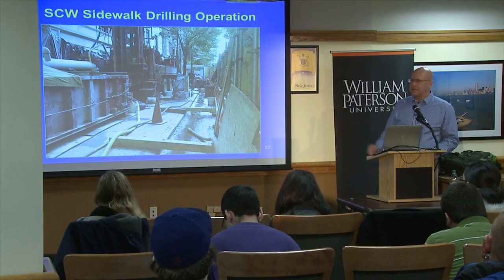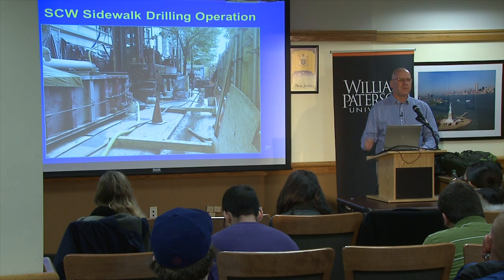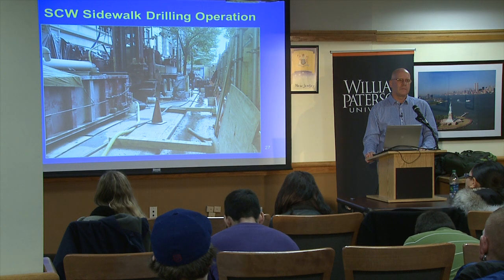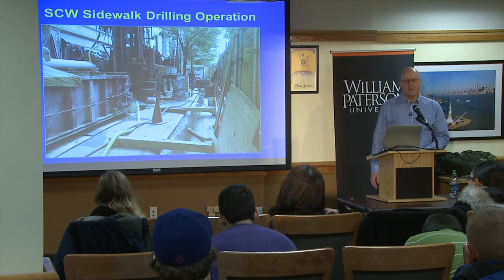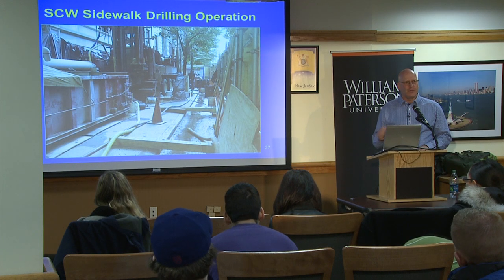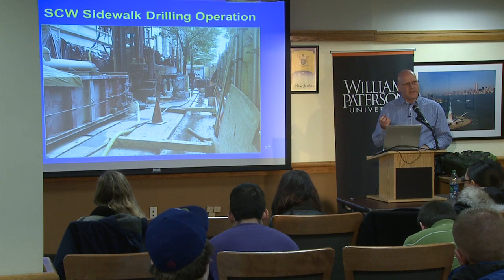Now, we couldn't have heated and cooled the whole building this way. There would not have been enough frontage on the building to put in enough wells to do everyone's apartment. So for this one duplex, since they're going to have extra energy, where does the extra energy go? Does it just stay in the system until they use it? It's not extra energy. Again, all you're doing is relying on the earth to reject heat or to draw heat, and there's no energy involved.